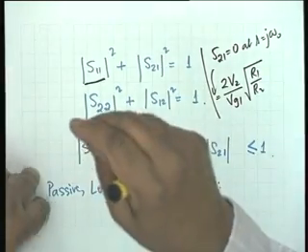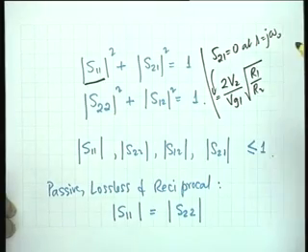That is, all the power that is fed from port number 1 comes back. Now, such a frequency at which S21 is equal to 0 is called a frequency of zero transmission, or simply a zero of transmission. So, at a zero of transmission, the magnitude of S11 is equal to 1.